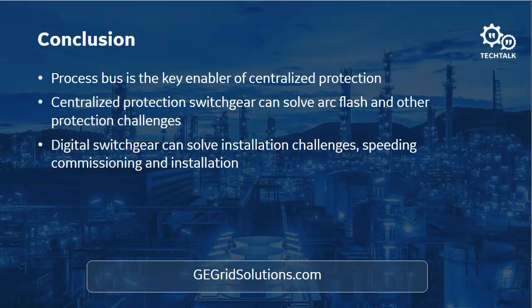So I would say if you are looking at the requirement that you want on your protection and control IEDs, at a minimum, you should look for 61850, the protocols of 61850, both station bus, GOOSE messaging basically, report control blocks through MMS, and process bus, either 61869 or 61850 9-2LE as a requirement for your system.